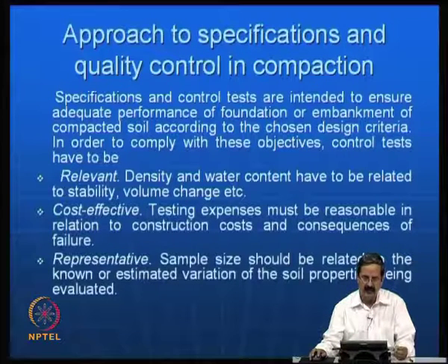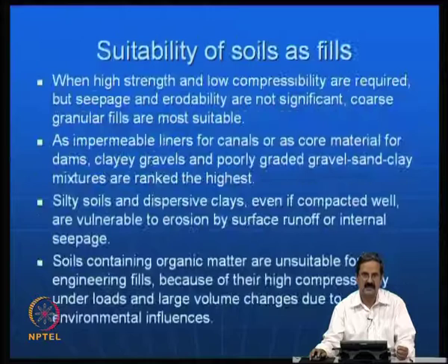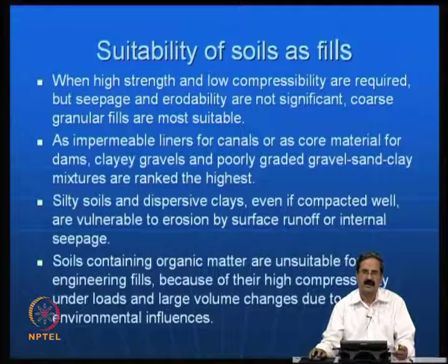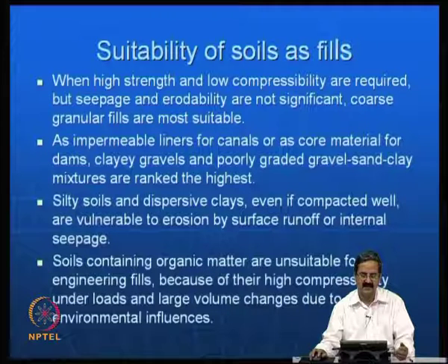So, when you are trying to have proper specifications and quality control, some of these points should be borne in mind: they should be relevant, cost effective, and representative. All these criteria need to be met. Before we go further, we must see why some of these specifications are required. For example, in some cases high strength and low compressibility are required, but seepage and erodibility are not of significance. So, coarse granular fills are okay.